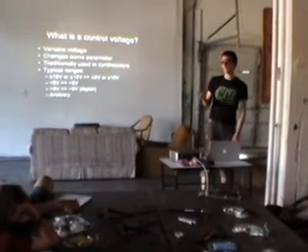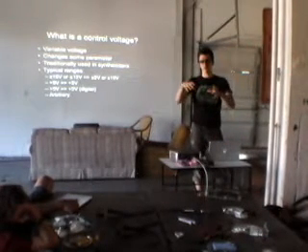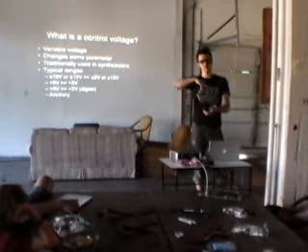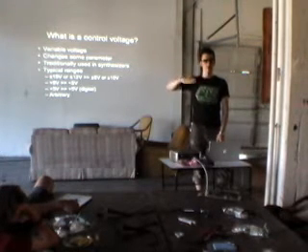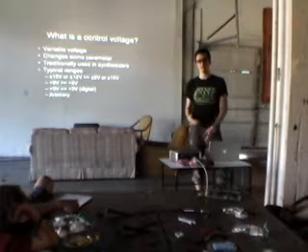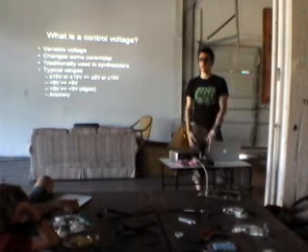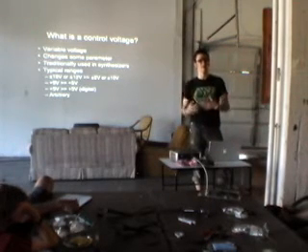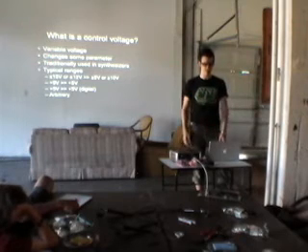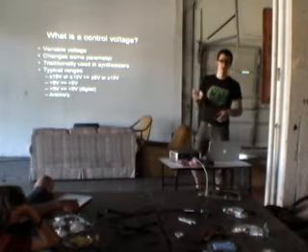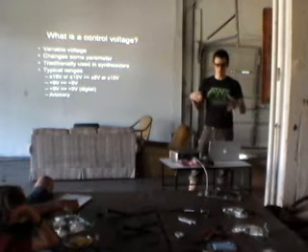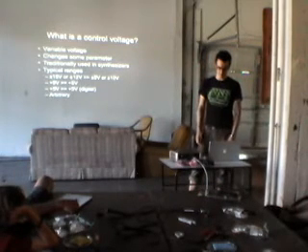If you ever hear an oscillator where the frequency sweeps up and down, or it pops up and down, the frequency just alternates, it's probably voltage controlled in some way. They might not really think it is, but in a way, it probably is. And most synthesizers, like analog synthesizers, use voltage control in some way.